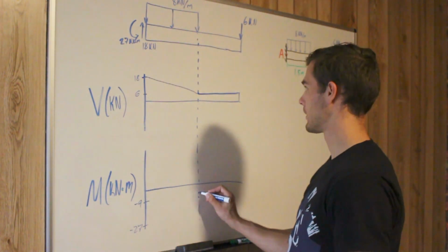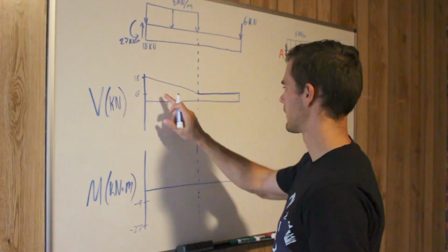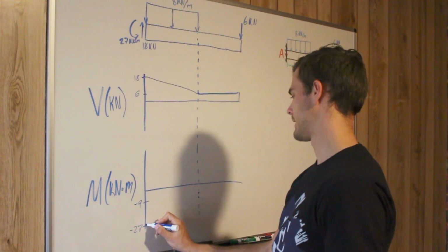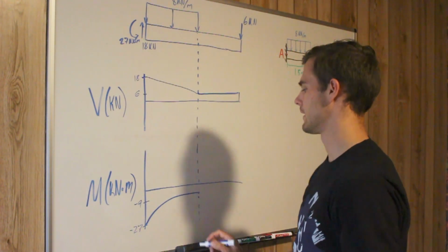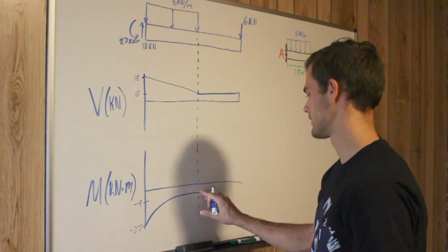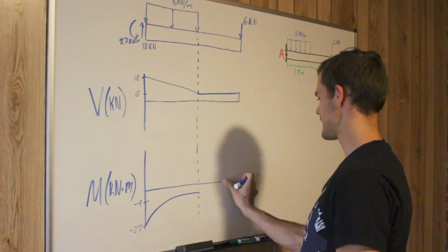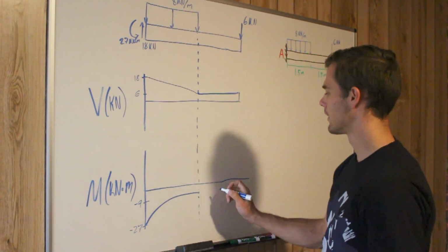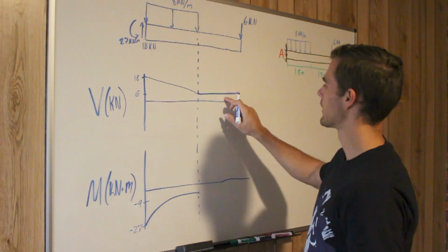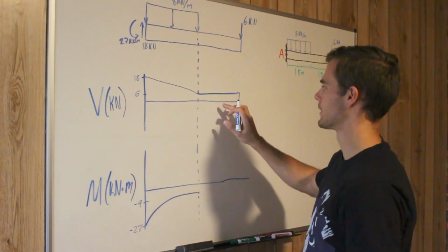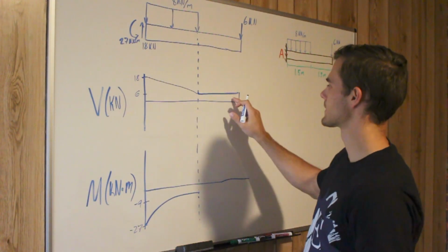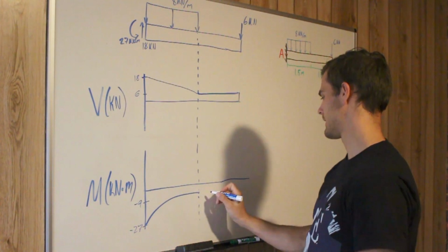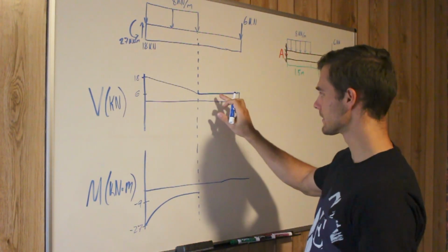And so we'll draw a point here. There's nothing changing in our shear diagram besides that function line, so it's going to look something like that. It's concave down, it goes up to negative 9. And then here on our moment diagram, draw that a little straighter, we have just area under the curve here, and so the area of that is 6 times 1.5, that's 9,